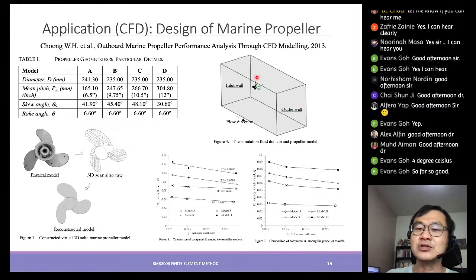For example, remember you have to set the boundary condition. So you may have a large enough volume in your simulations, and when this spins, nothing is actually spinning, so you have to tell the fluid to flow through it. So when it is so-called spinning, he can check the efficiency, the thrust efficiencies, and the coefficients between different models of the propeller.